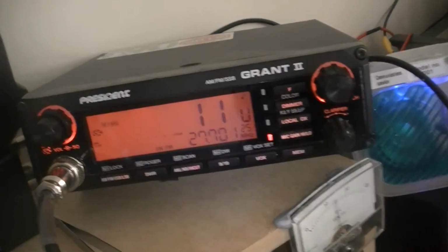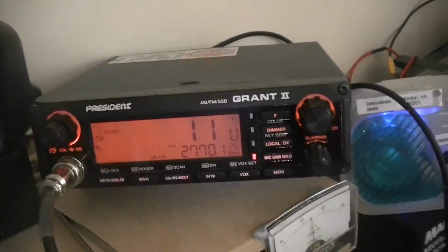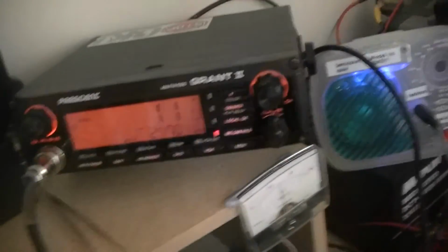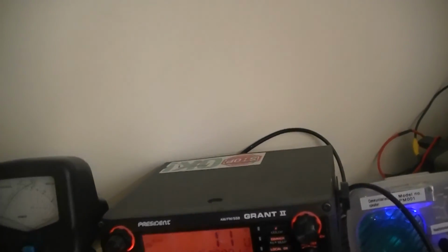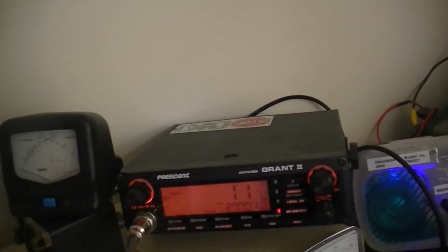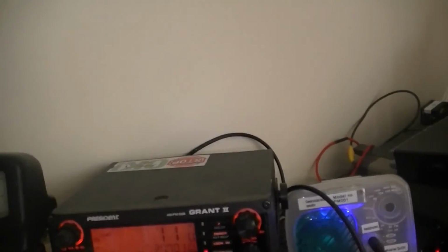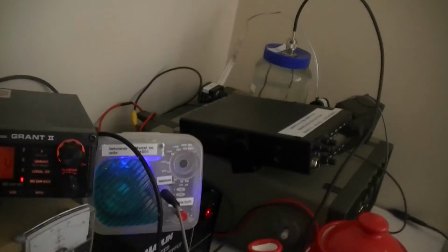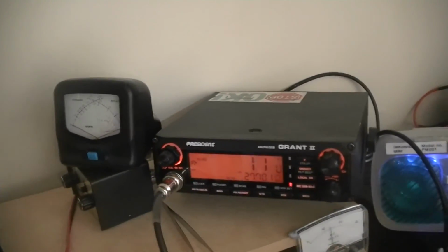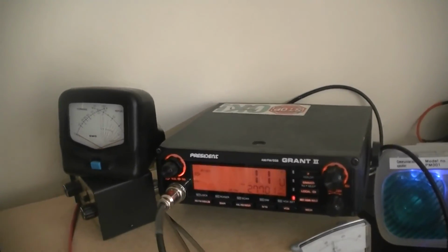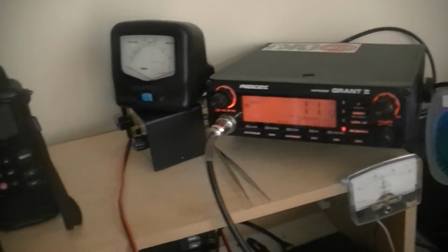Quite a lot of mains hum on that, but that's because it's all into dummy loads and everything, and it's picking up the hum presumably from that power supply. Both radios are actually connected to that one power supply, which isn't ideal because I don't have another power supply in here at the present time. There are other ground loop hums that can occur as well, but there's a way to hopefully eliminate that. There isn't a ground loop isolator on the interface at present because I don't think it needs it.